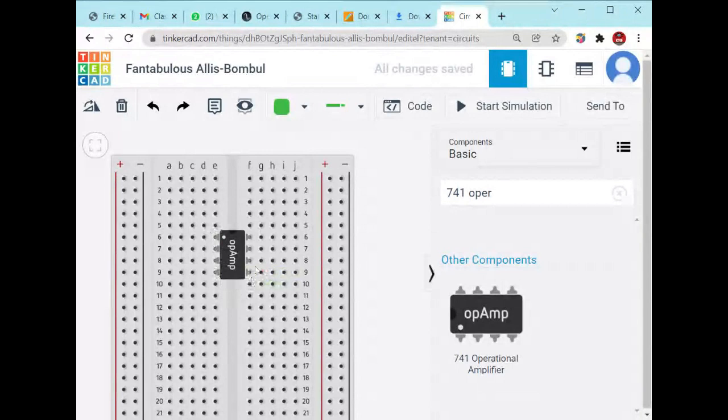So how will you count? You will count in a U shape. It will start from here and it will end at this particular point. So you will count like a U shape: first, second, third, fourth, fifth, sixth, seventh, eighth. The eighth pin is not connected.